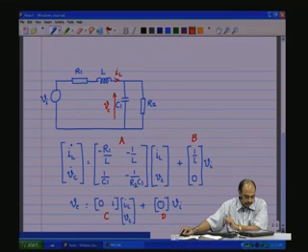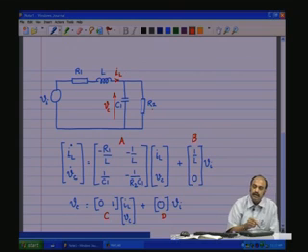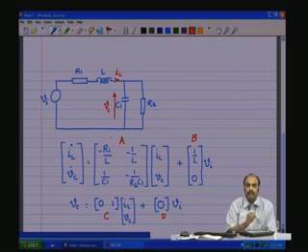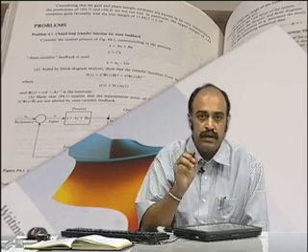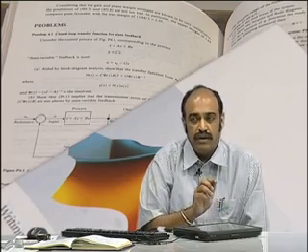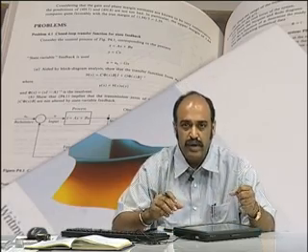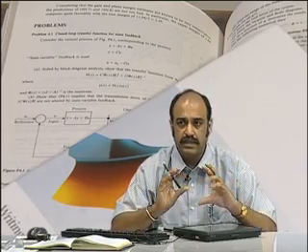So, you see that the circuits that we have been discussing and also the models that we modeled last class, in the last session, we can put them in the model, input the A, B, C, D matrices and view the performance, view the characteristic features in the three domains, that is the time domain, the frequency domain and the pole-zero domain. And note that all these three domains are going to give you very useful information about the circuit, even though the circuit and its responses are always existing in the time domain.